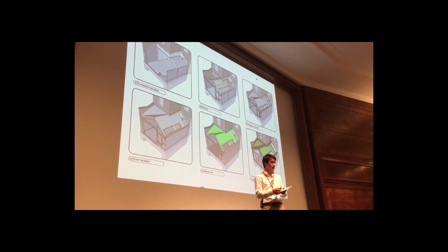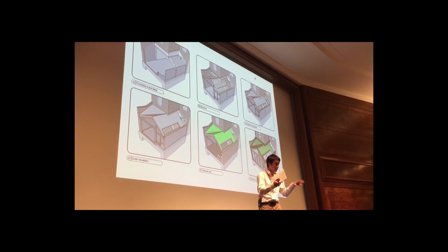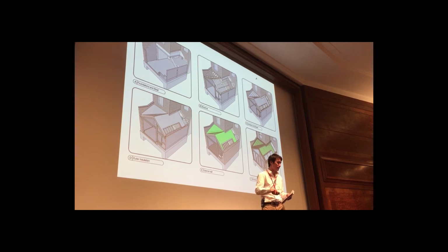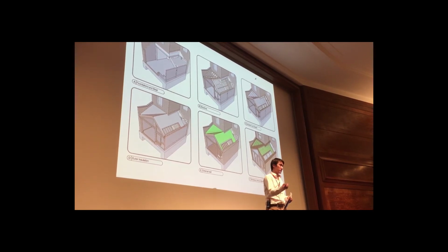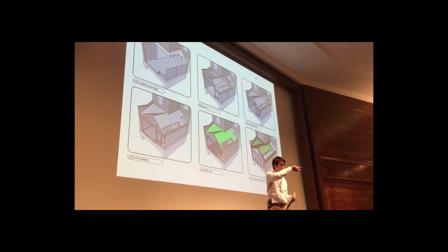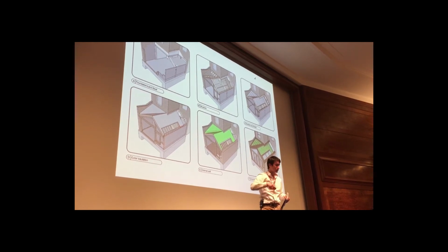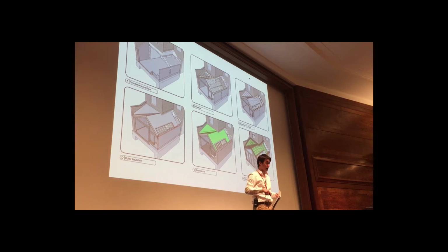Is it going to be quicker for me to model one building, have all these sections taken out and updated in real time, or is it going to be a lot quicker for me to just put in the sheet materials in 2D, in Layout, just on the drawings that I need them?